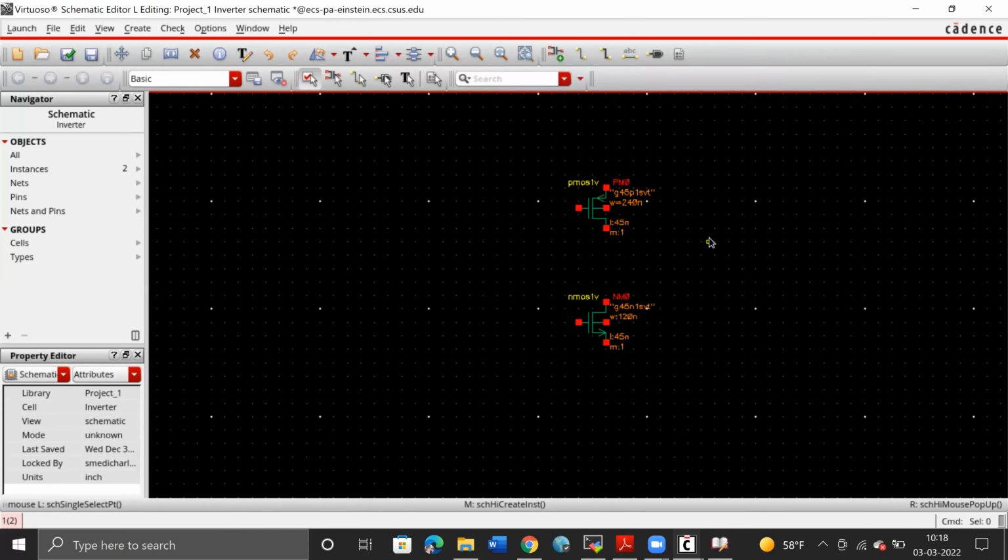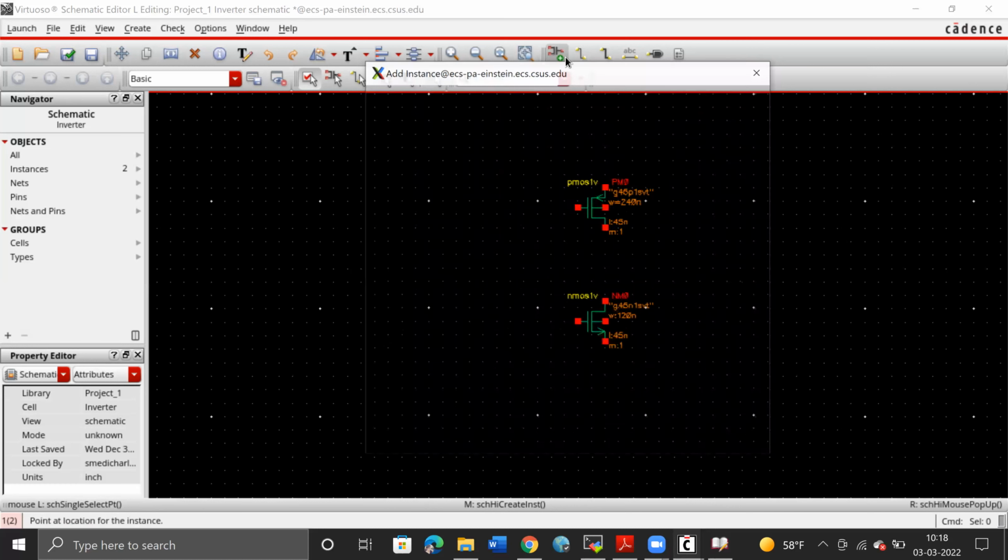Now in a chip, there is huge noise and sometimes there is a VDD bounce or a ground bounce, for which you would want to simulate and check the capacity of your circuit. For such situations, you would want to use a pin for giving the supply voltage and simulate how the circuit works based on the signal that's given as VDD. So I'm going to use both of them right now just to see how it works.